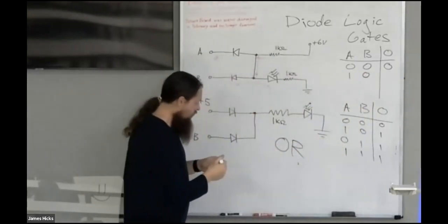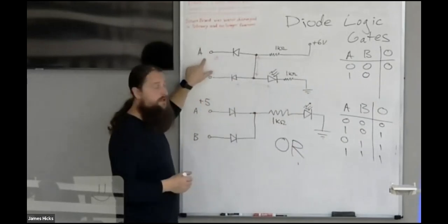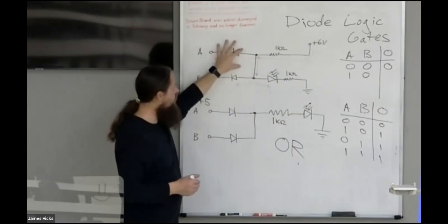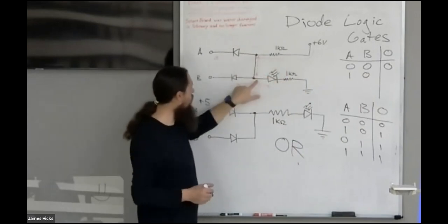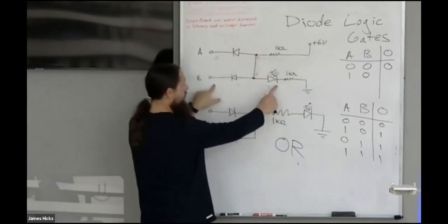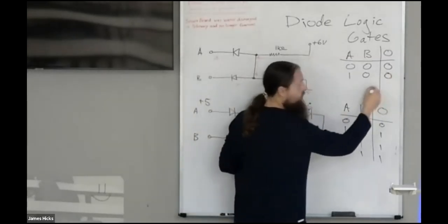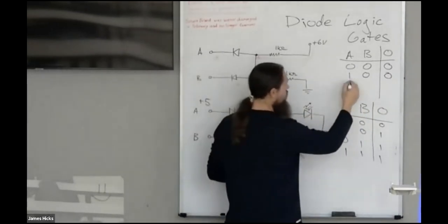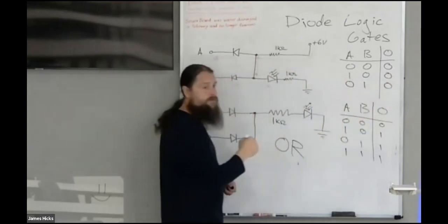Okay. So make A logic level high. If I do that, then it's reverse biasing this top diode, which effectively turns it off. But you still have B tied low, so the current will still bypass the light-emitting diode. So it stays off. Symmetric for 0, 1: it still stays off.